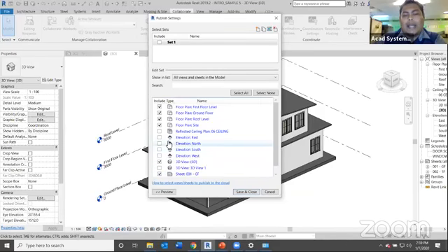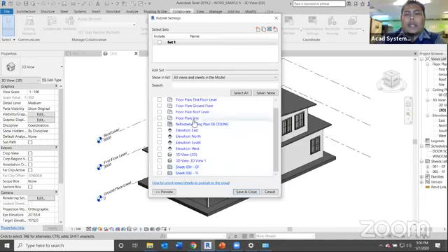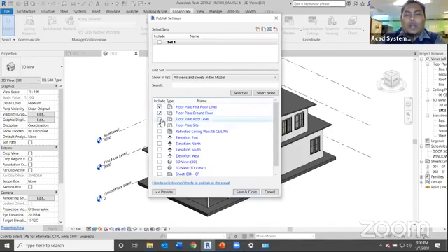So you must click any views that you want everybody to see, and it will be allowed in the BIM360 platform. Or else, if you keep everything empty, people won't see anything inside the BIM360 platform. So that's the way we control the items that we're going to publish online.